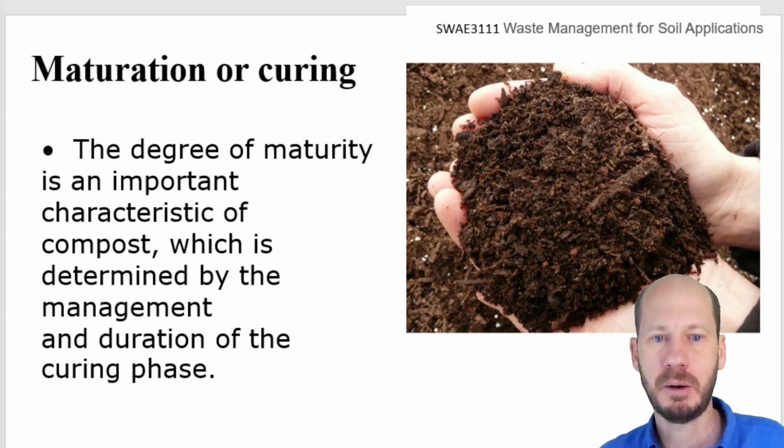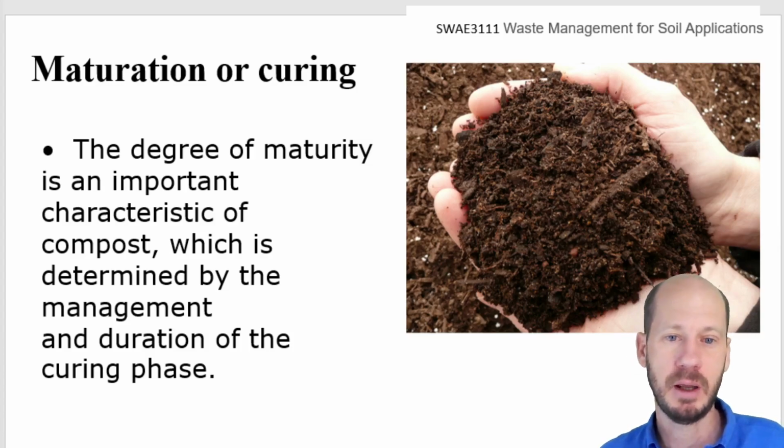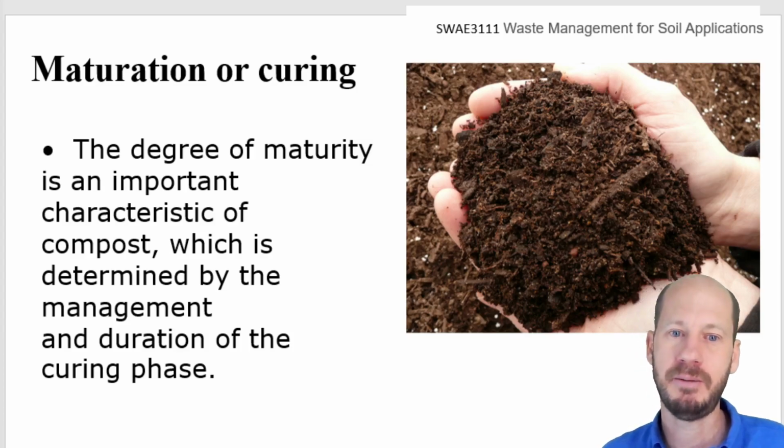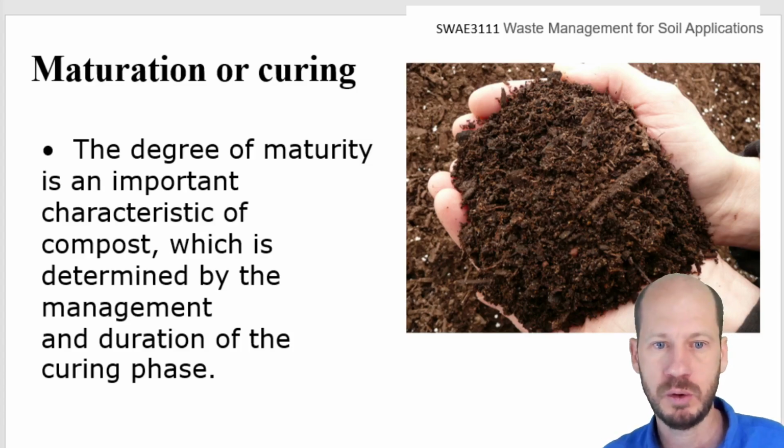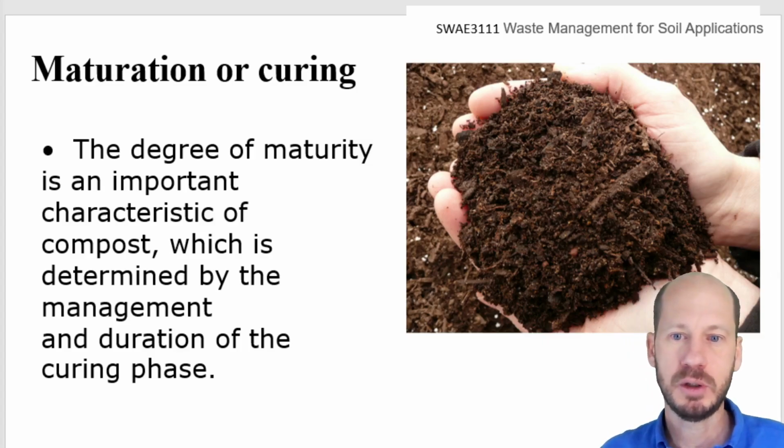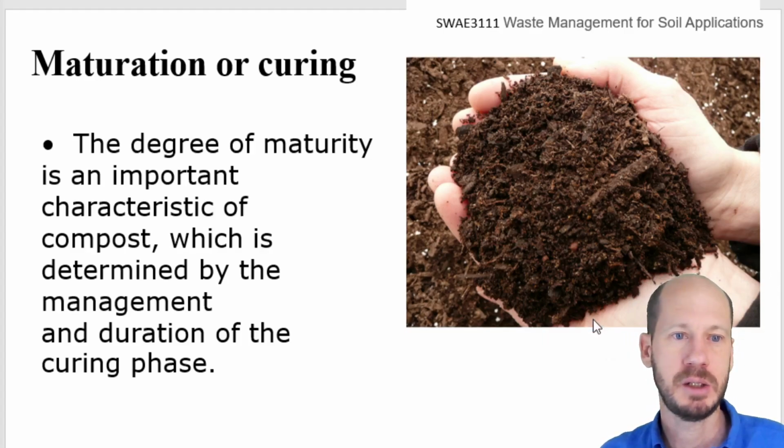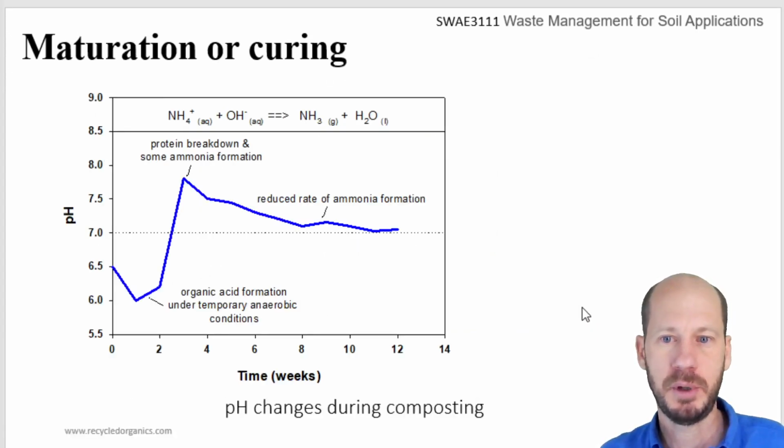And how do you detect that the thermophilic phase has ended? It is because there are no huge differences between the temperature of your material and the temperature of the environment outside. So if your compost is still generating heat, that is the first sign that your compost is not mature yet. The other way you can monitor the stability of this is through pH. So when the pH stabilizes near neutral, that's when you expect that your compost is very mature.